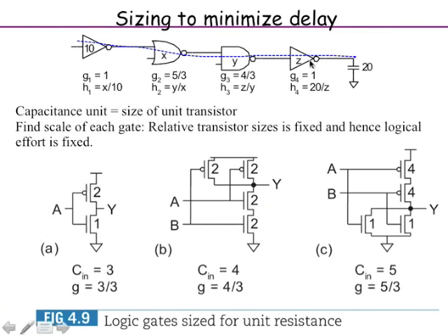Now typically you need to have these constraints. Input and output capacitances have to be given to you. If they are not given, there are many solutions. I mean, you cannot solve that problem basically. And typically in circuit design, the input could be driven from this inverter. It could be the output of a flop. There is a standard cell flip flop which is driving it, and that size perhaps is this 10. So that is fixed. You are not going to change that, and then you have to find the size for the rest of the thing.